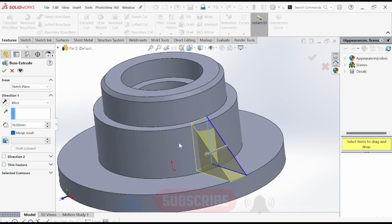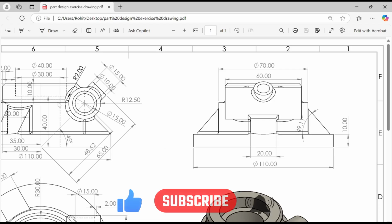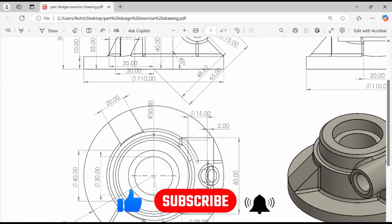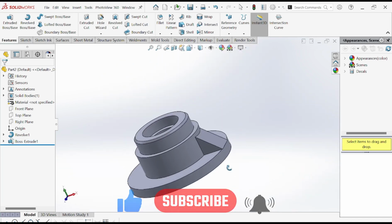Now we need to extrude this one in mid plane. We need to extrude this one in both directions equally. So how? Select mid plane, and what is the thickness of this part? It's 20. This part, it's 20 mm. So simply make this one 20 and make this one okay. Now here you see, this is our part done.